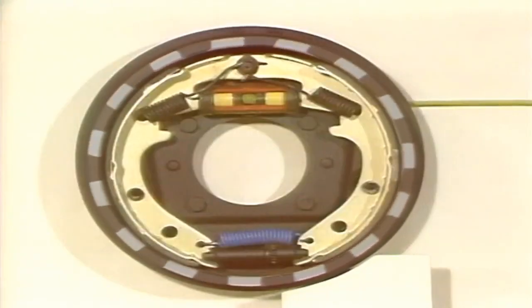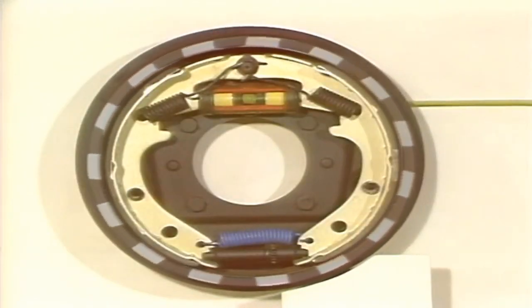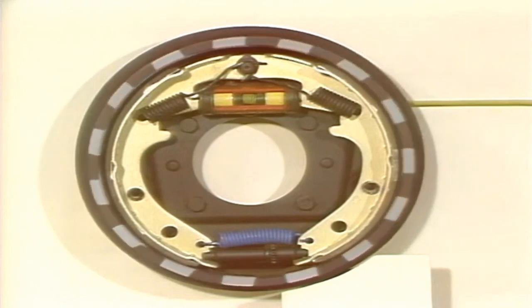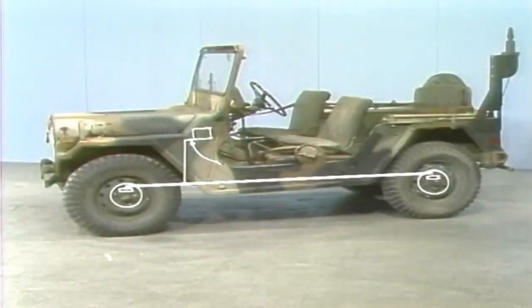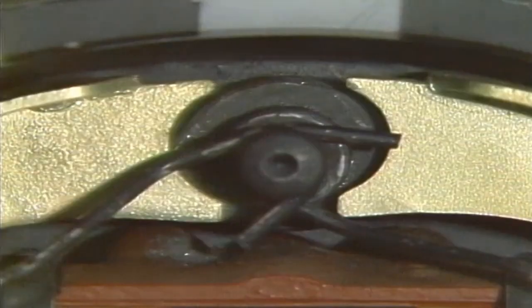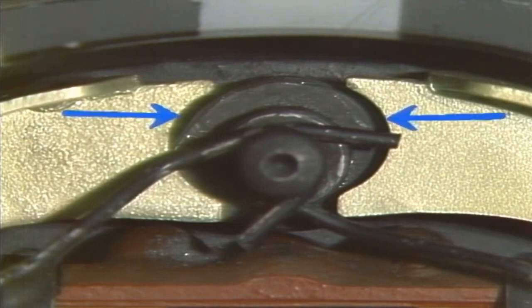That's why it's so important to follow directions in the manual for bleeding air from hydraulic brake systems anytime you work on them. There's something else going on in a drum brake system you need to know about if you're going to really understand how the system operates overall. When drum brakes are applied, both shoes initially contact the drum with equal pressure. This is the reason why the space on each side of the anchor pin is equal.